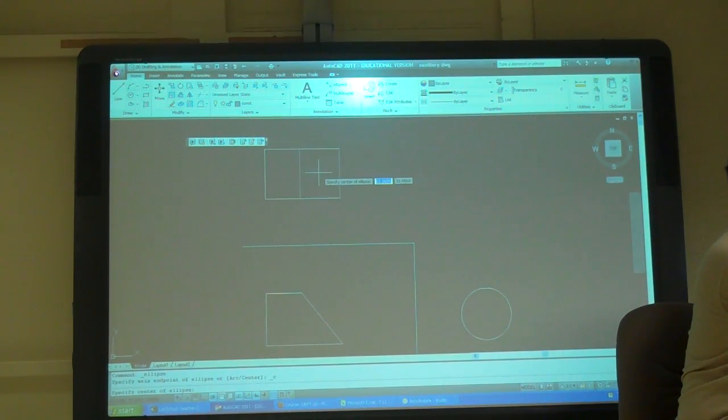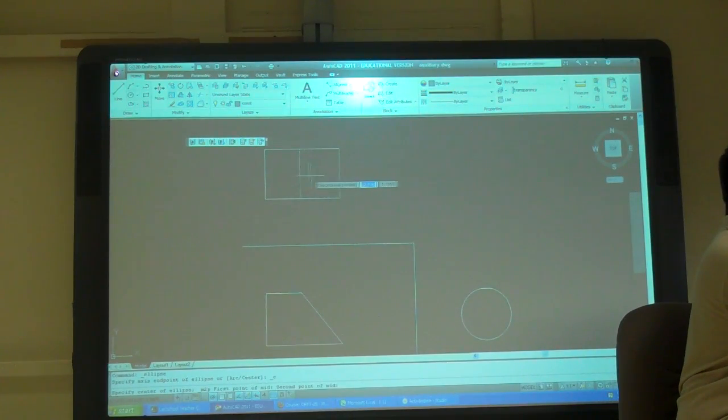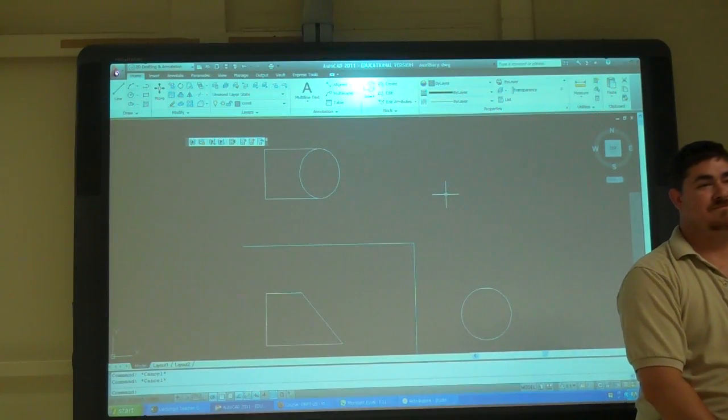How can I pick that point? Midway between 2 points, right? So I have a midpoint here and a midpoint there, and the circle's halfway between those two. So snap to midway between 2 points, there. Now I can pick this side as side 1, that side 2. What's the difference on this? Doesn't matter, I could have done either way. I'll just take that and that, go bye-bye, trim, there. From that to an object.